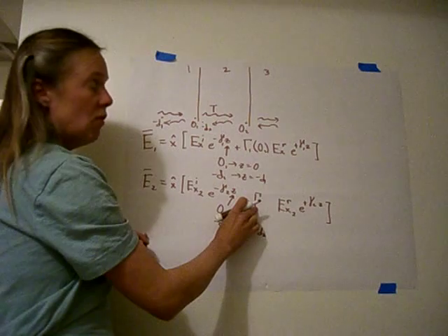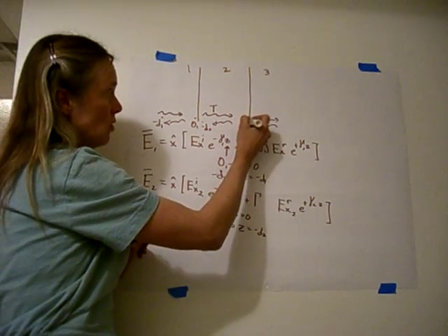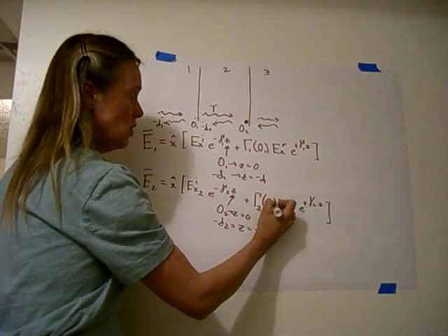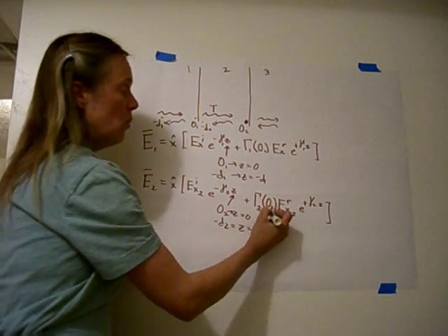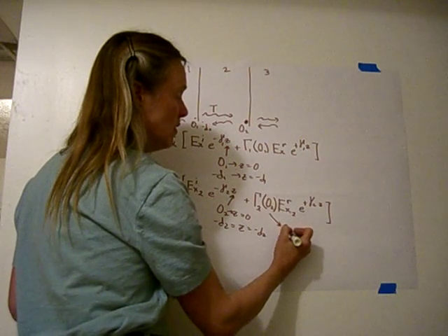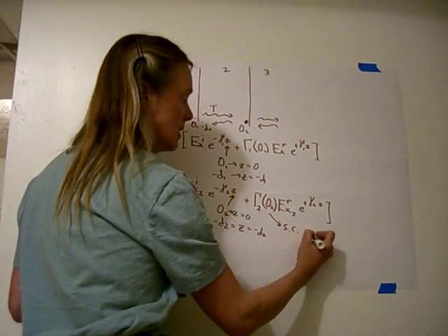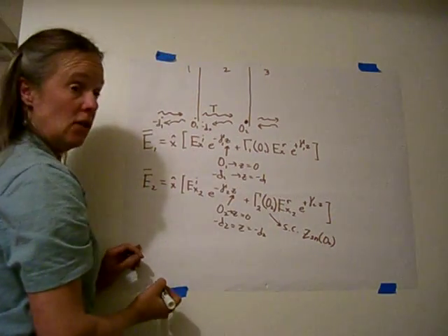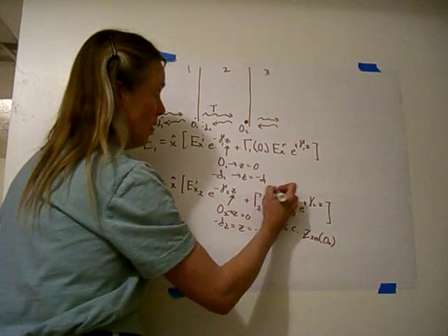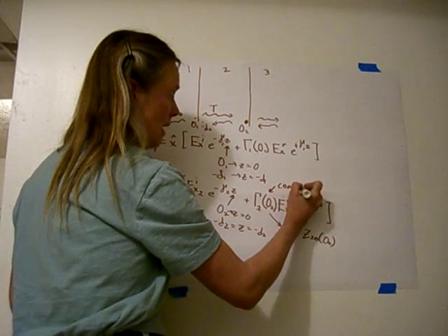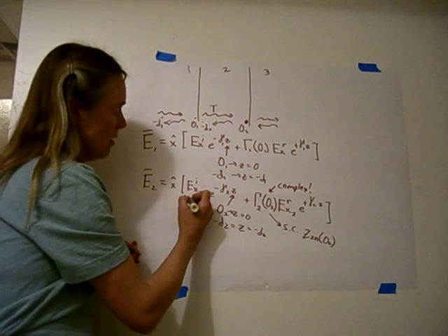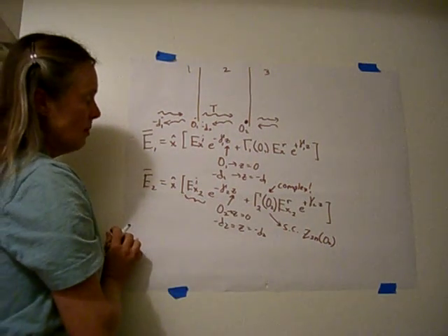The reflection coefficient that we're interested in is the reflection coefficient right here at O2. So this is the reflection coefficient in region 2 at O2. Remember, we were able to find that off the Smith chart when we looked at Z2 normalized at O2, and we would read its magnitude and its phase. Remember, this is complex. It has a magnitude and a phase. Don't forget the phase.